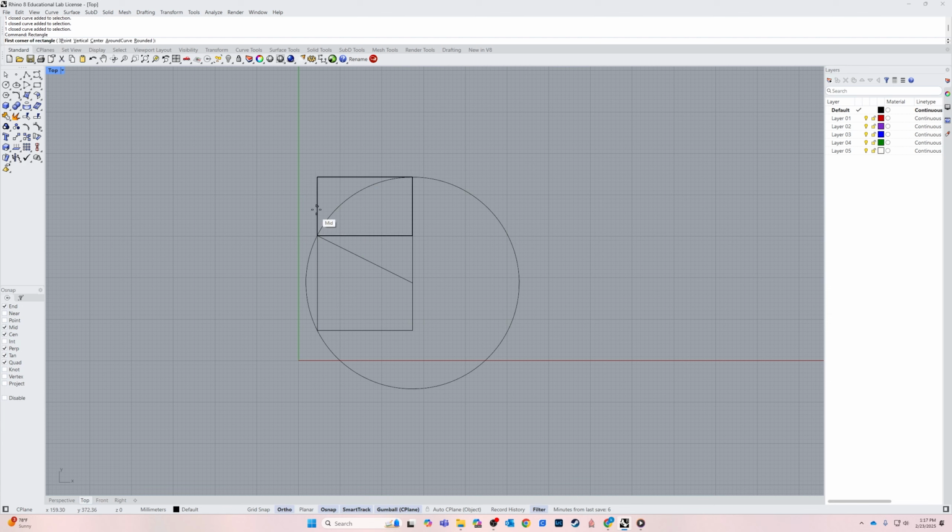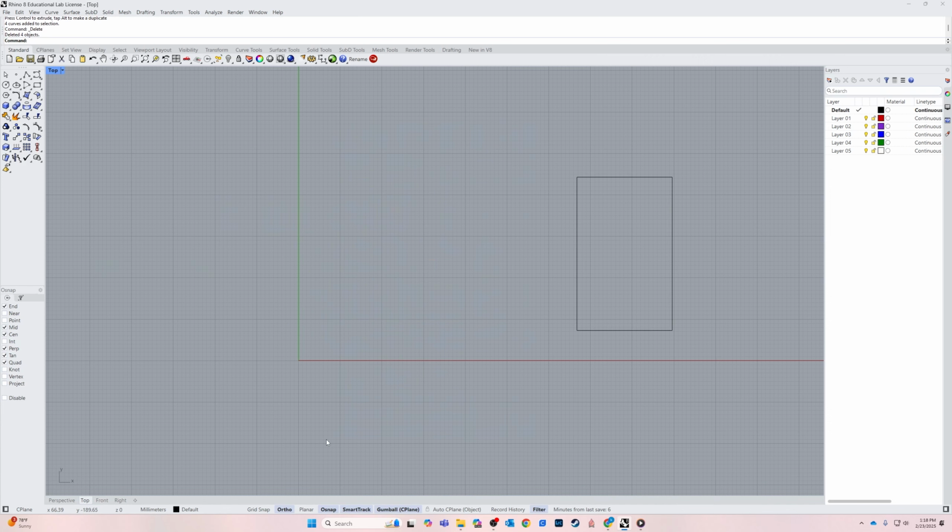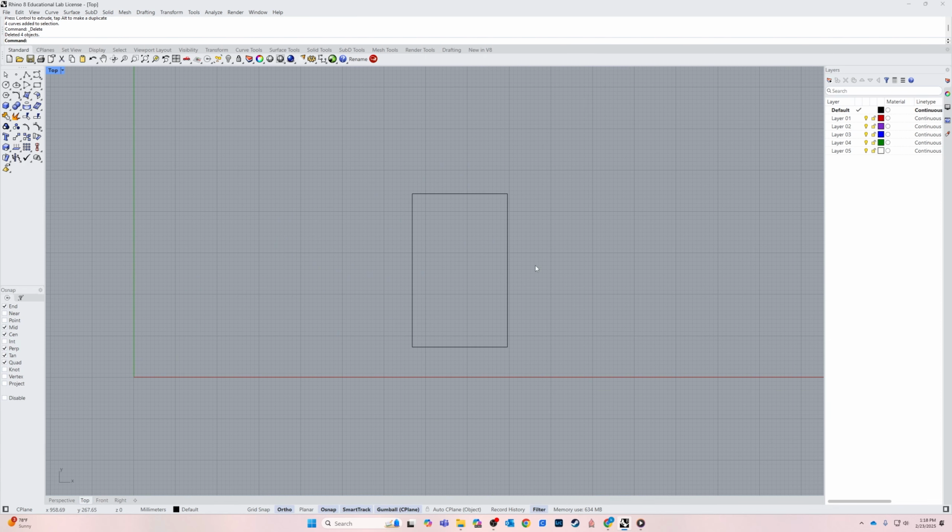So I'm going to type rectangle and just use that as a guide from there to there, and then click here, and it gives you several different options, because you've got curves on top of curves. So I want this curve as my reference. Then I'm going to go ahead and delete these. Perfect. And I'm going to copy it 3 times. So I'm going to hold down Alt, and I'll put one over on this side too, because I need 3 of these to make my 20-sided die.